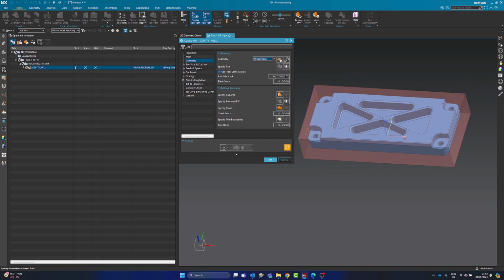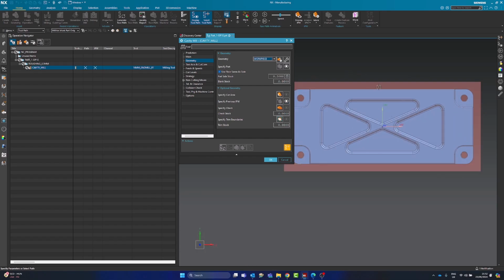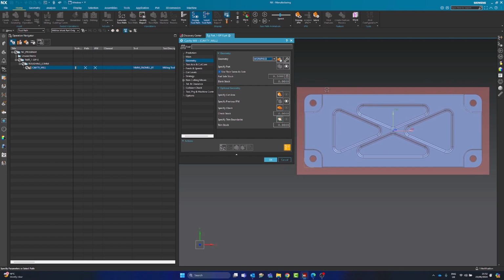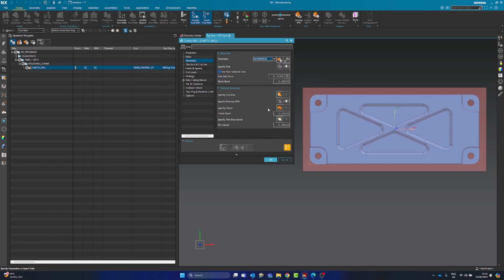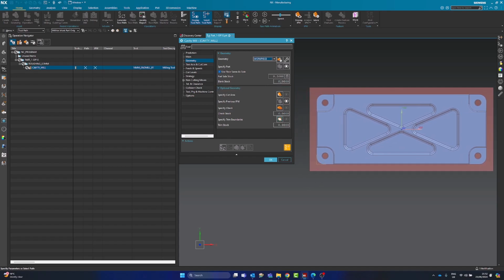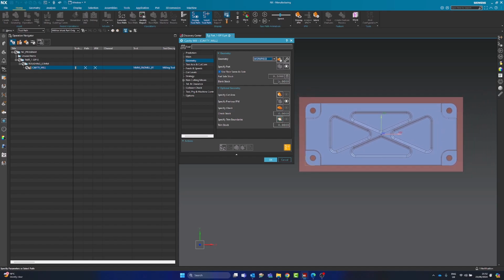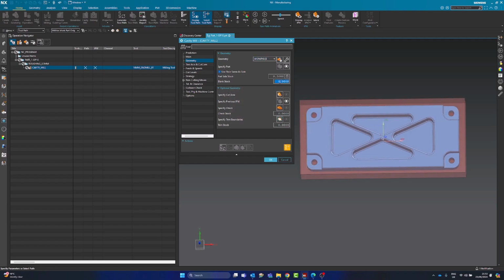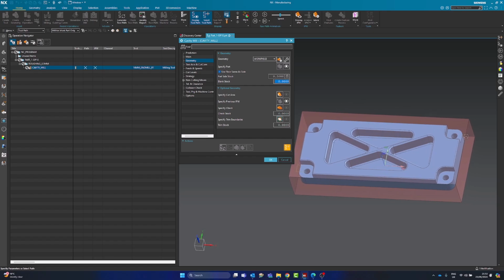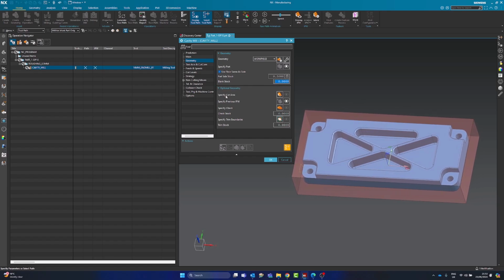Blank stock. What blank stock will do, when you look down at your stock here, if you add 10 mil of blank stock, it's going to offset our part by another 10 mil. Normally it's useful in your first operation like we've got here, because sometimes, as you probably well know, a billet can hit the machine and it might be 10 mil bigger in reality than it should be. You might have ordered 100 mil thick, but the billets come in 110 mil thick. What normally happens is the machinist would run it and your tool would take a really heavy cut and possibly break it or fling the job out of the vise. So with blank stock, you can add 10 mil onto here or whatever you desire, and it will offset the stock for you and do bigger cuts. I'll demonstrate that in a minute.